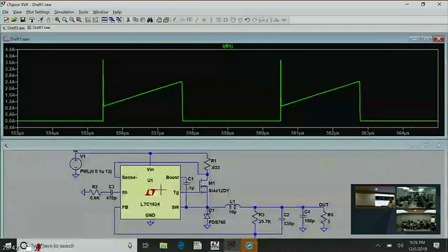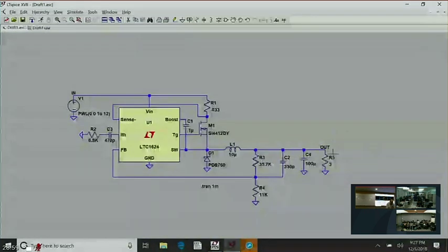All right, so it's great you have this high-speed blanking, which gives you a very short minimum on time, but that very short minimum on time still isn't zero. And it might be too long under some operating points of the controller. For example, if the output is shorted to ground, then when you turn this switch on, the inductor is connected between the input voltage and ground. That's the biggest voltage in this whole system, and it's straight across the inductor, and the current ramps very fast. And during that minimum on time the current might overshoot the maximum allowed current. And if the current goes through the inductor, it also goes through that switch, then it could blow up that switch.